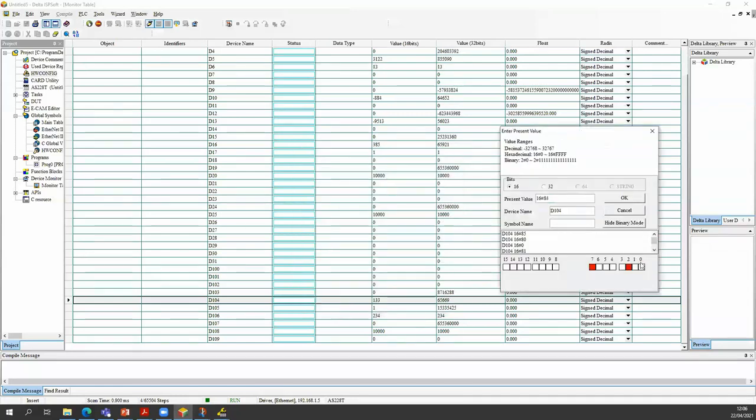If I give it another run, it's not going to run, because in absolute positioning it only moves if the target differs. When it's in relative positioning, it's going to go every time. But if I set it back to absolute positioning, then it's going to go 2 rotations back from 30,000 back to 10,000.